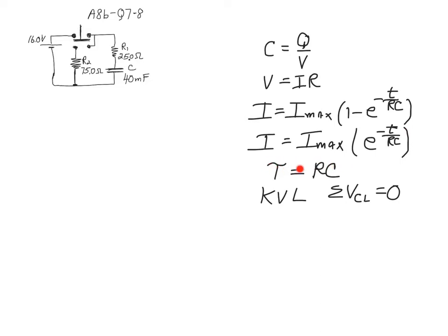What we mean by the time constant is this: as we start the clock, when the time reaches this value, then t over RC will be 1. And when the time reaches twice this value, then t over RC will be 2. And so that period of time, whatever it is, 4 seconds, 4 milliseconds, 4 microseconds, whatever that time is, will be what we call the time constant.